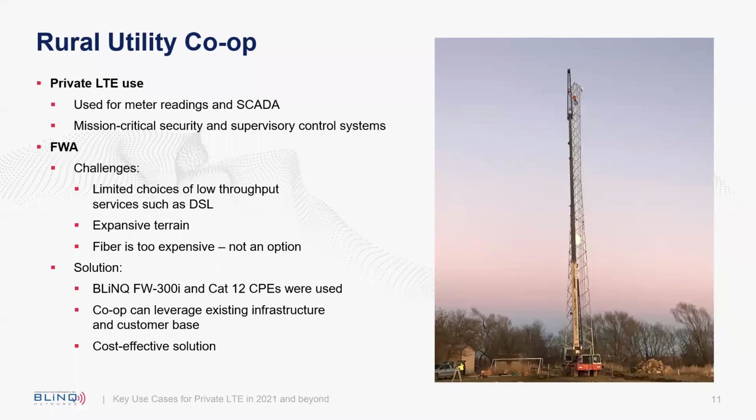Certainly some of the proprietary technologies out there can go a bit further, but they're really hampered when it comes down to line of sight. That's why we're seeing a lot of customers that are currently using 5 gig moving back towards CBRS, simply because their customers may have had line of sight 3 years ago, but now the trees have grown up and they have non-line of sight and their connection is really weak.